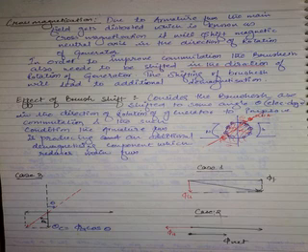Actually, when you say these are all the conductors under the influence of North Pole, how is the armature flux? Like this. Here armature flux is like this. So, when the brushes are not shifted, brushes are on MNA, how is armature flux? See the second diagram of your notes of armature reaction. Brushes are not shifted. How is the armature flux? It is just downwards along MNA, right? So what is armature flux doing then? Only cross magnetization. Slight demagnetization, that is a separate effect, that is due to saturation. There is no brush shift.